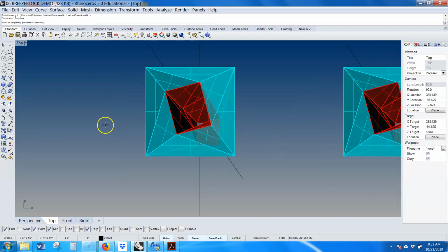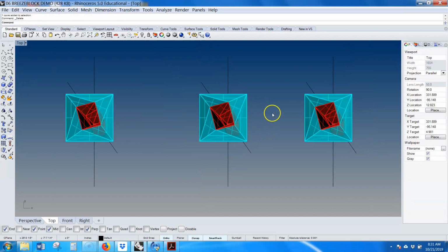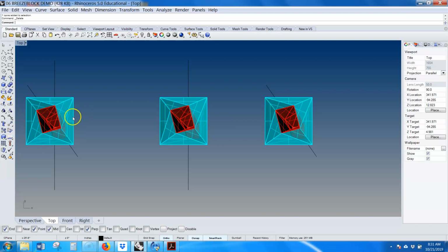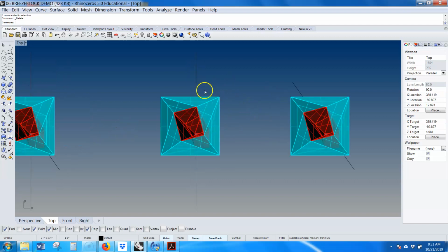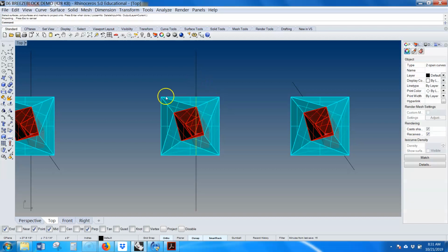I could also cut one through this way. Usually when you try to document a 3D condition, you cut a section through at least two points. Okay, so this one I'll make the straight cut, and this one I'll make the oblique cut, right? So those overlap like that. This is like my key plan, yeah? So a few ways to do this. One, I could simply type project, and I can select this, and select this, and I can project it.